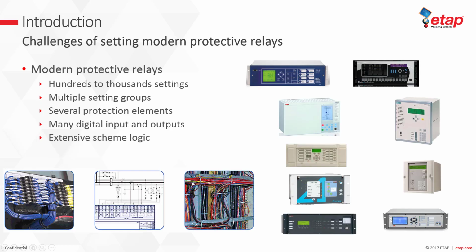Today's microprocessor-based protection relays offer many functionalities. However, they require a large amount of settings and complex scheme logic to be operational. Multiple settings groups are available to adapt protection settings to different system configurations. Many protection elements are provided for different applications.